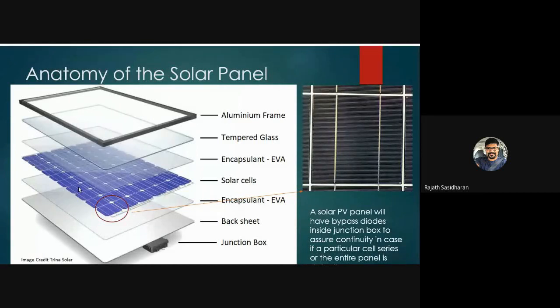It's because in different parts of the world, it hails, and there is a snow load as well. So it's just for impact resistance. Okay. It is given with the backsheet again, and everything is encapsulated in an aluminum frame. Why aluminum? Because of its corrosion resistivity.